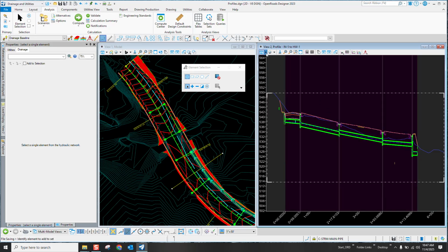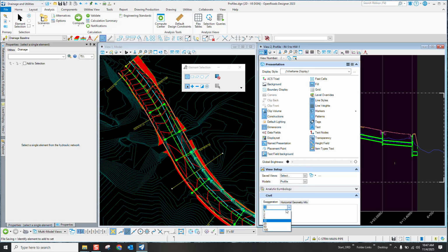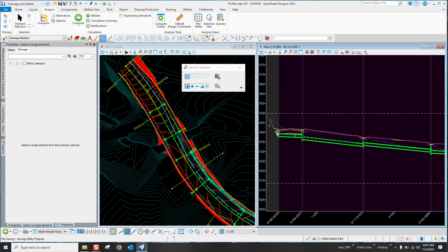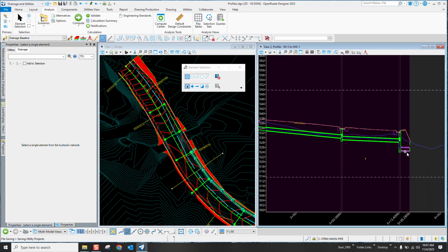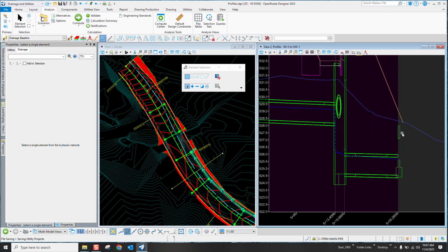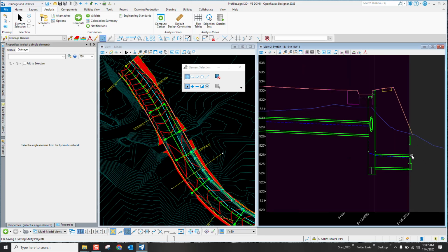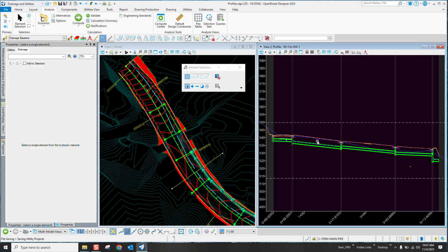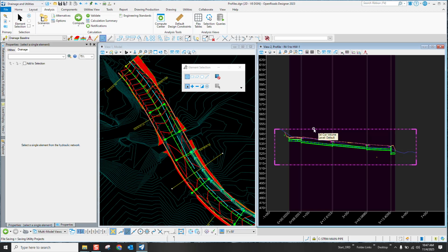I'm going to adjust the exaggeration from 10 to 5. And that looks a little more reasonable. Here's the head wall on top of the pipe and the footing. Looks like I need to make an adjustment there. There's a mismatch. So 3D cuts are editable. You can select it. And then the manipulator, when it turns red, you can adjust the window.